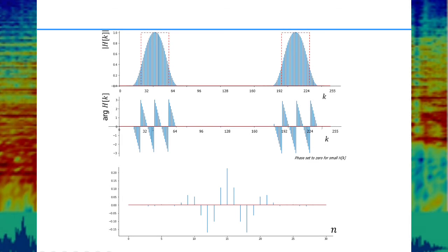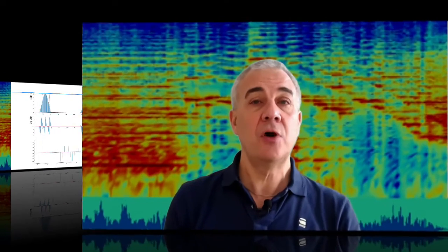Here is the resulting frequency response of the adjusted impulse response. Indeed, we now get an approximation of the desired bandpass filter. And we also see that the phase decreases linearly with 0.12 pi radians per DFT coefficient, with phase wrapping at minus pi. I think you understand that there is no unique solution to this filter design problem. The order of the filter, the spectral leakage and the spectral resolution must be traded off. All signal processing software packages include procedures in which you can specify your frequency response preferences, and the filter coefficients are then found through numerical optimization procedures.